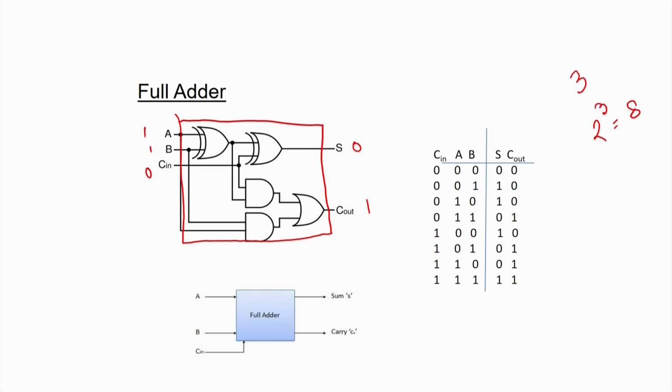Now, we have to see one more thing. Say these are some logic gates or electronic components. When we put signal 1 and 1, we are not going to get the result over here immediately, because these electronic components have some delays. It needs some time, and whatever time is required, we say this is the propagation delay of that particular block. Here we are simply using an exclusive OR gate. So, this XOR gate will take some time to give me the final stable output over here.